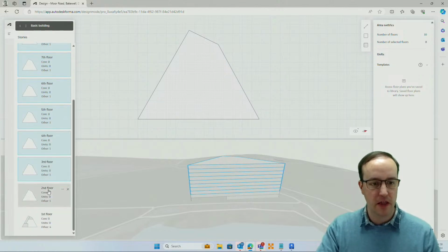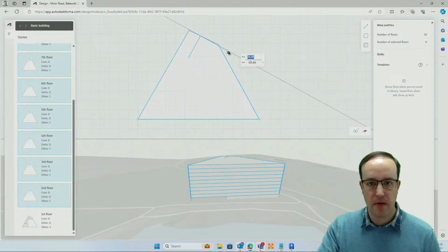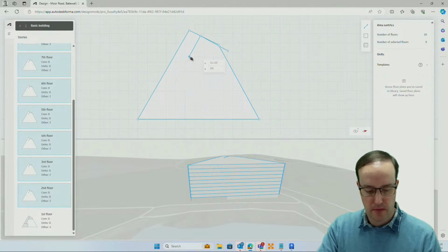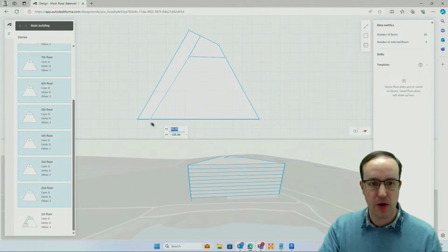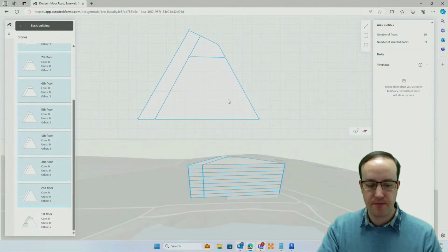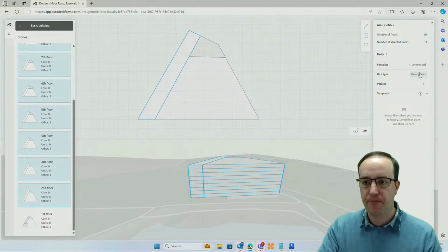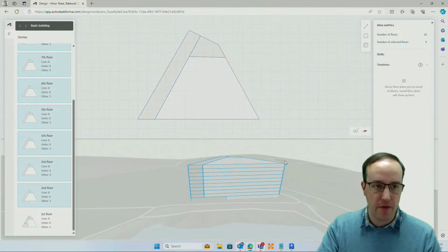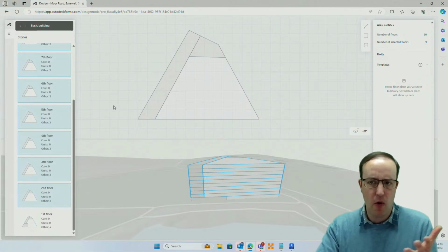And I'm going to select all those other floors and then say that all of those other floors have this same stairwell over here, and also this same corridor, but it runs full length. I'm then going to select those 2 rooms and say that, much like the other ones, they are corridors, so on and so forth. You can see that this has changed every floor plan. So you can do one at a time or in bulk.